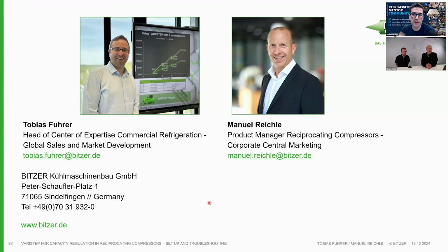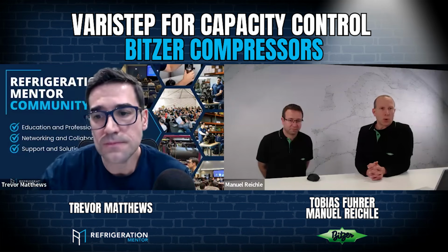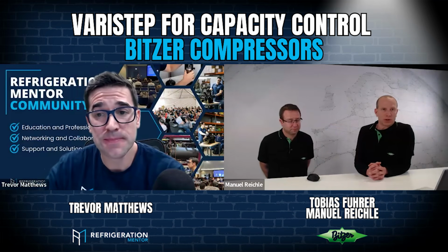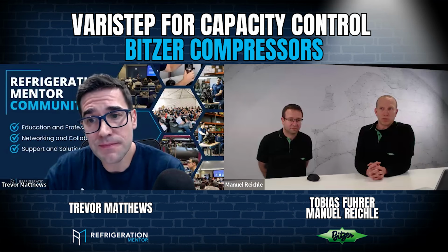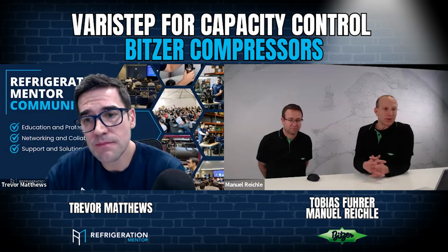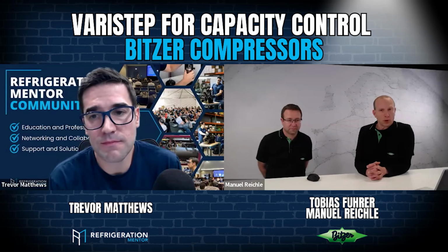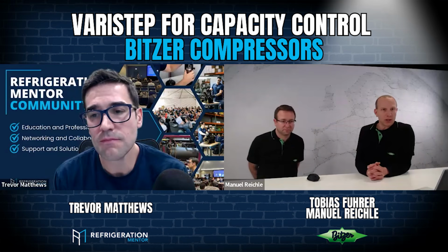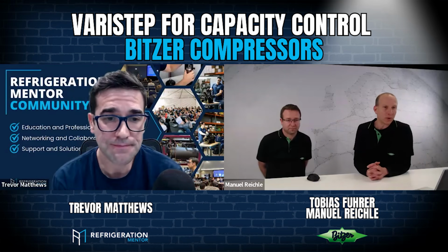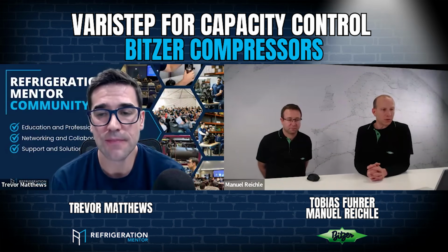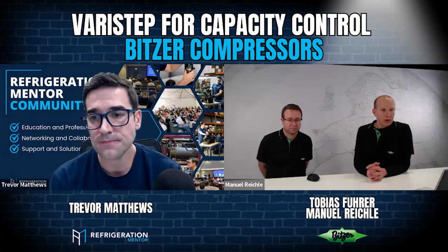What are your thoughts on CO2 in larger applications, heat recovery, things like that? Yeah, that is coming more and more, and I think there are pros and cons. Some people really think that ammonia is a bit more difficult for service, due to the properties of ammonia. But we do see CO2 more and more. I could even think about a combination of both, right? I could see ammonia in the medium temp stage and CO2 in the freezer stage, like in a cascade configuration. That would also be a nice combination.